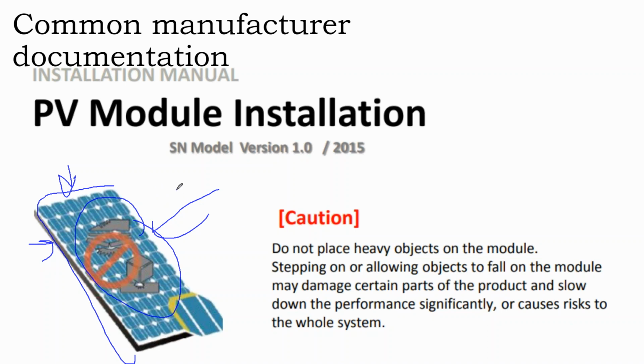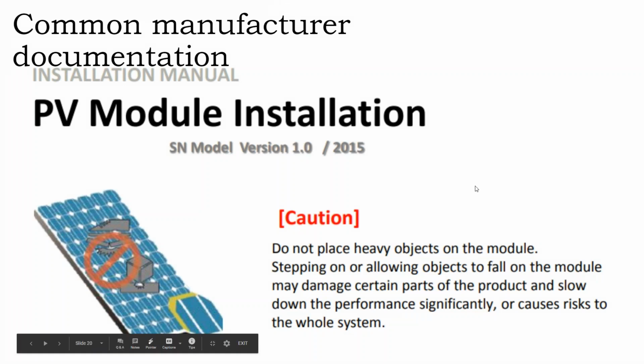And it's, no, that middle section of that module, of that array there, is not intended to have a 200-pound elbow point load pressure on it. It can take a glancing blow of 1-inch hail at 40 miles an hour, but it can't be stressed and cracked down 1 inch because some person's putting their whole body weight at a particular point. So you don't see that in the spec sheet. That's going to be more in the module installation manual.